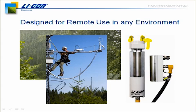So then you can just take a cloth or the shirt tail off your shirt and wipe off the windows. You can run a swab down through the tube and reassemble the instrument, push it back together and screw it closed, and that's all there is to cleaning the instrument. And again, having put instruments in the field for a long time here at LI-COR and having people on staff who've been out in the field trying to keep things running for years, we appreciate how hard it can be sometimes with a closed path analyzer to keep the optics clean.